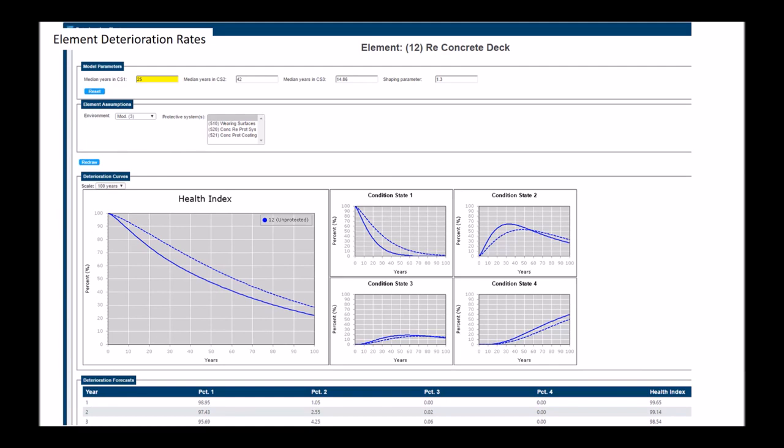We've done our best to pick defaults, but as an example, steel protective paint lasts about 15 years in Alabama's marshes and about 45 years in Utah's arid desert. So the deterioration rates should match the environment of your agency and your experience. If you need some help trying to set these values, some states have contacted Bentley to have us help determine what your deterioration rates should be. Just contact the help desk if you're interested in that.